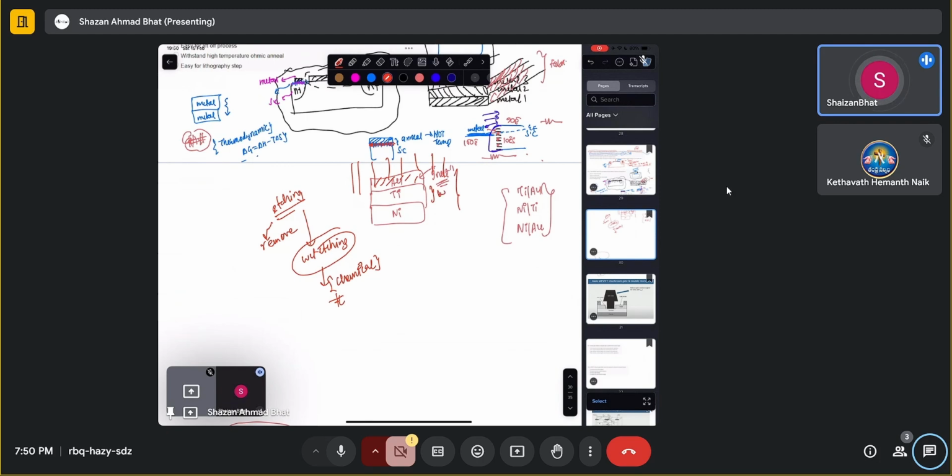This titanium can be used as a barrier, let's say, so that the electrons cannot flow from here to here, or it cannot affect any of the electrons in the nickel. And this will be the actual metal then, which will be providing the field effect towards the channel. And then if you have a MOSFET, you can have oxide. If you don't have an oxide, then it will be directly connected and it will be making a Schottky barrier.